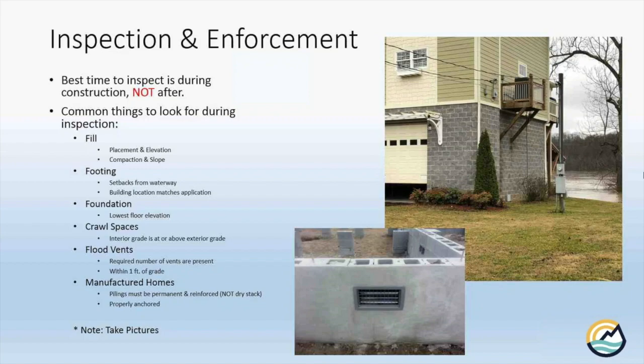Want to look at the footing. If there were any setbacks, are they far enough away from the roads or waterways? And does the location actually match what they said on the application? We want to look at the foundation. So what's that lowest floor elevation? Is it going to be up high enough once they're done?